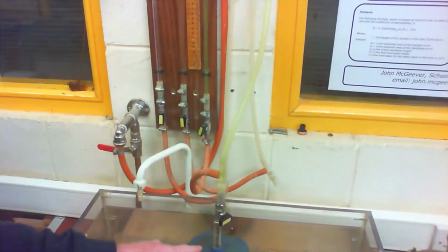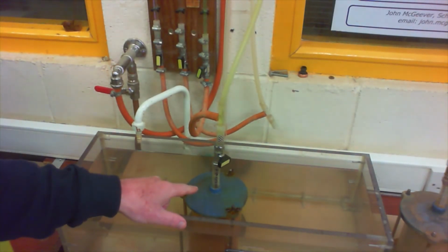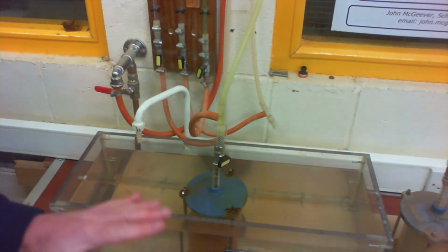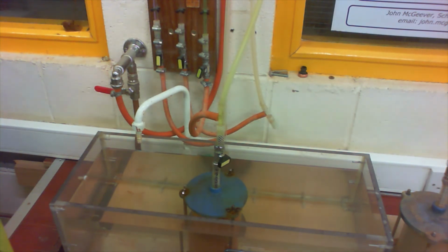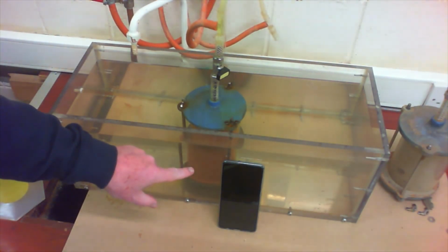The other information we need is the diameter of the sample, which is 100 millimetres, and the height of the sample inside the tube, which is 12 centimetres. So with that information, we can then use the logarithmic equation in our notes to calculate the permeability of this sample of more impermeable soil, possibly a kind of silty material. In the tutorial that's going to follow, we'll do our calculations for a number of runs of the test.